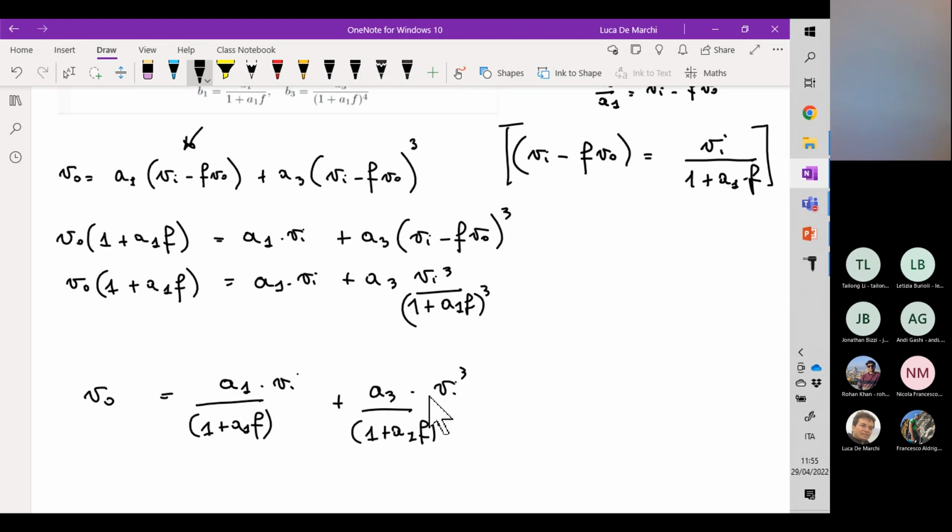To estimate the pole position, what we should do is to find the roots of this denominator here. In some cases, this can be quite tricky, okay? Because we may have the information related to A(s), to F(s), but we may not know the effect of this addition of the unit.